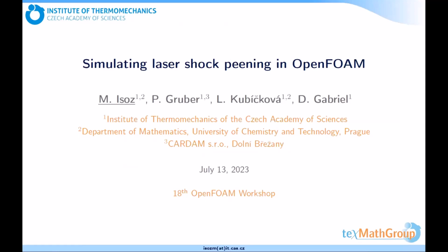Quite a few questions we were thinking. And Python, how does that impact the OpenFOAM solver? It's doing the laser part, right? Yeah. We basically have our laser boundary condition and Python, and it's simplified to just select the phases on which the pressure will be active in the next iteration, and Python is doing that. And also it takes care of some data transfer, because we keep a lot of data during simulation to see how, for example, we first put one pattern, then we put a pattern with a slight transition, and we need to see the internal variables through that. So it takes care of this data transfer and of selecting phases.